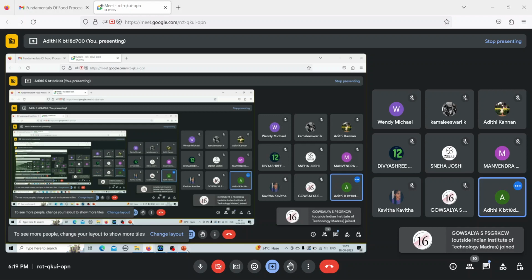So based on the pressure, the boiling point of the feed will vary, and here it is given that the boiling point temperature is 50 degrees Celsius. So let's say that the temperature inside the evaporator, let us call it as T1. So T1 is equal to 50 degrees Celsius. I am converting it into Kelvin. So plus 273 is equal to 323 Kelvin. So when you send the feed in, you will heat it to 323 Kelvin, or if it's already entering at boiling temperature, you will just supply the steam to convert the feed into vapor and a concentrated product. So the vapor that is going out will also be at the same boiling point temperature, that is at 323 Kelvin.